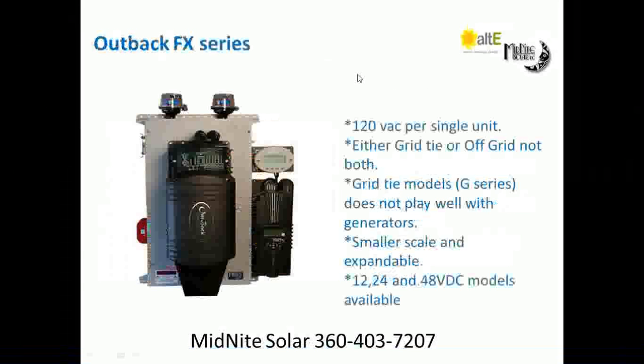So we're going to be a little inverter specific now, and I'm going to talk about the FX series. The FX series comes in either an FX or a GFX, and the G stands for grid tie. Now there's also a V that can be thrown in there, which doesn't mean anything as far as whether the inverter sells or not. Basically that means it's a vented versus a sealed unit, so it's going to make it a little more powerful is the difference.